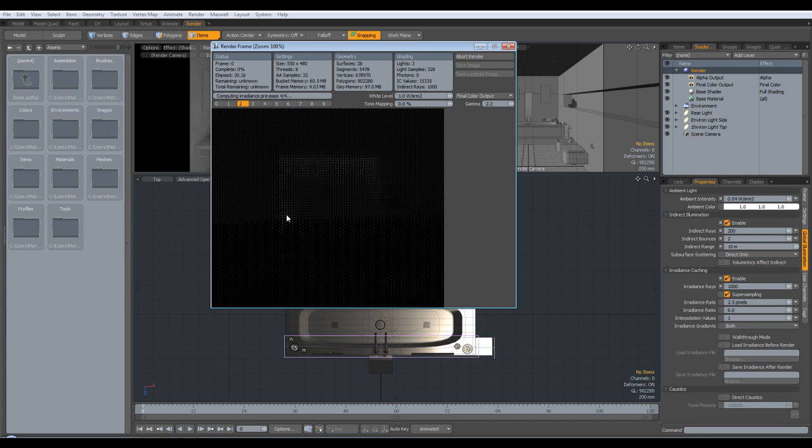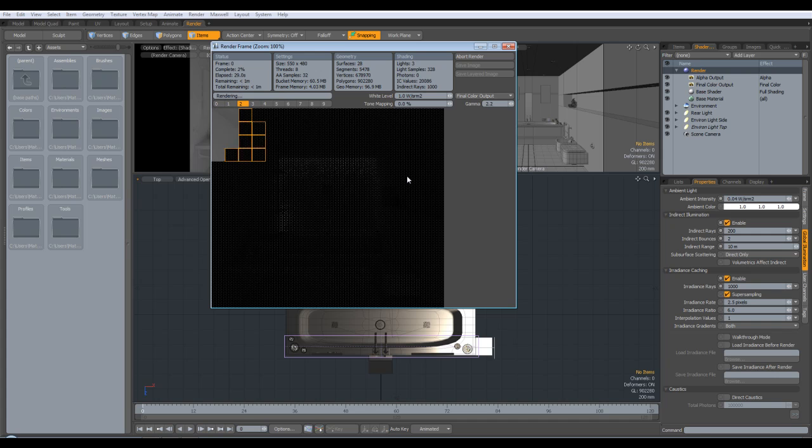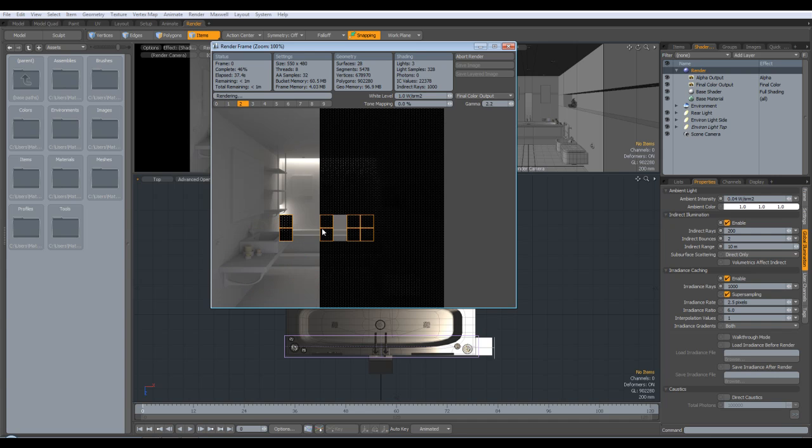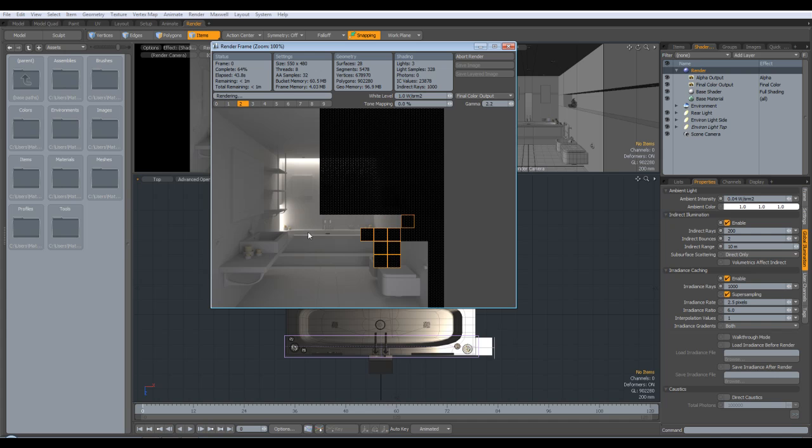If you've got any areas which are blown out, now's the time to cut the lighting down a bit. But don't forget, all the walls and all the materials at the moment are a default 80% grey, almost a white colour. So as you start adding materials, the light is only going to get less, so you don't want to bring the light down too much now, because you'll only end up having to push it up at a later date.